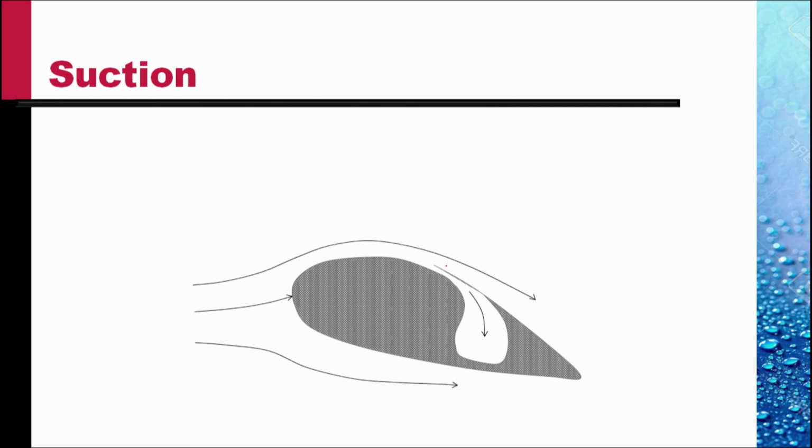So within the wing, we have a sink where we suck the air out. So the slow moving boundary layer is sucked into there, and the main flow comes down and it is more energetic, so the separation is delayed.